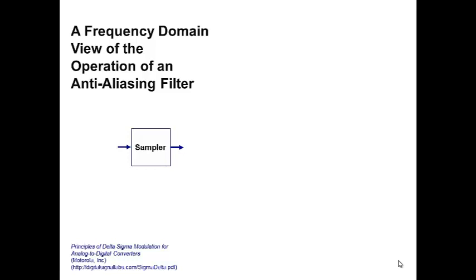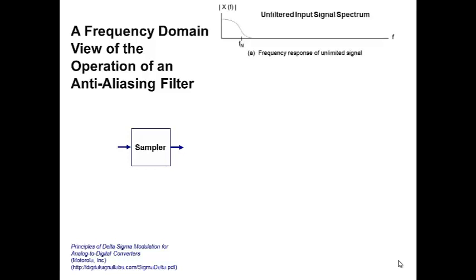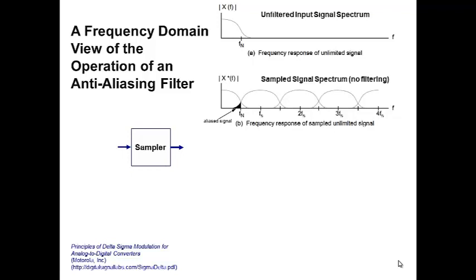Okay. And here's the picture. If you have a signal that has some higher frequencies, at least something that's above the Nyquist rate, we know that if you just try to sample that, we're going to make these spectral copies. And where those spectral copies overlap, this stuff is aliasing and distorting our signal. So we would find that unacceptable.